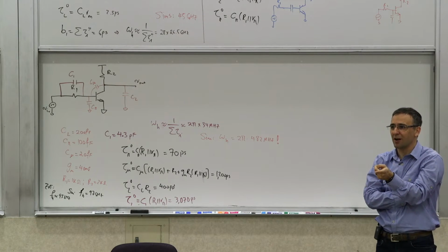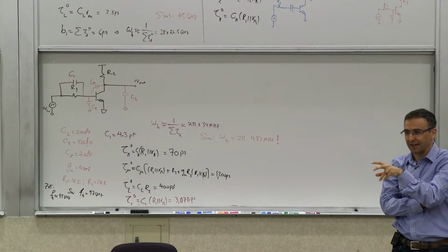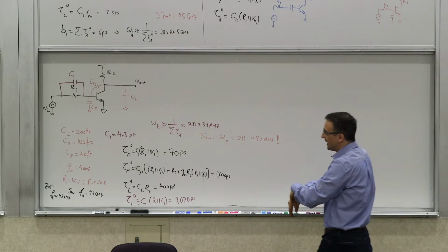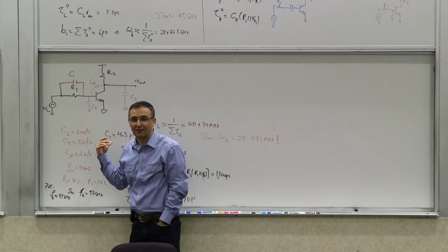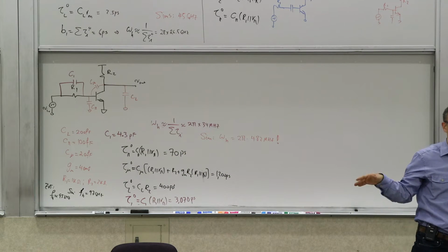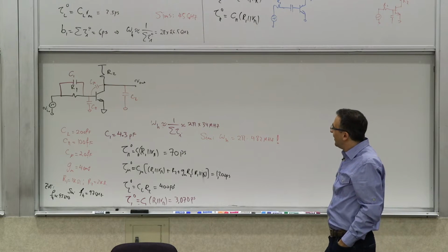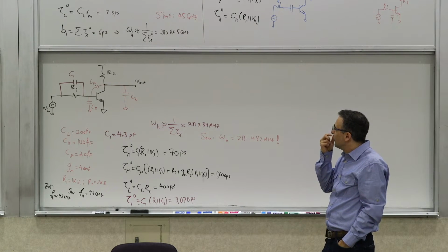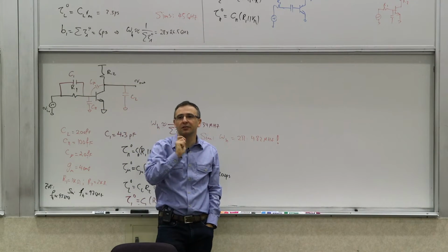We'll see how we arrive at that in a short while, how you pick it. Now if I had picked it to be any other value, like say 7.5 picofarad, this would not have happened. I mean, the gain would not have been as high. I picked the right value, really. But what happened is that you introduced another zero. So what did I do with that zero?